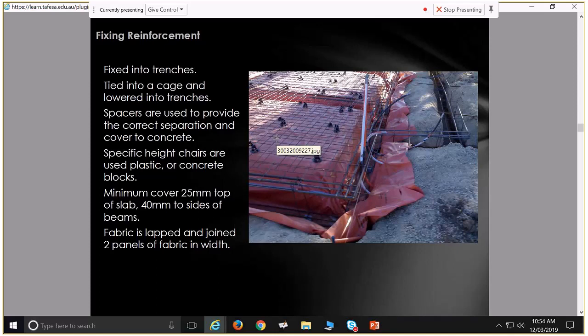But this enables you to get that accurate measurement of the height of that steelwork, away from the edge, in a fraction of a second. So it's like, boom, that's 25 mil there, or at that height, we're at 40 mil. So you've got different heights on your chairs that enable that adjustment to happen. Everyone checks the height of the soil. So is that the easiest way?